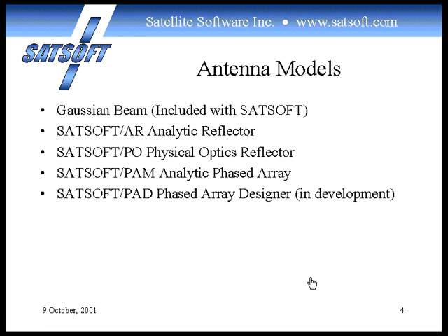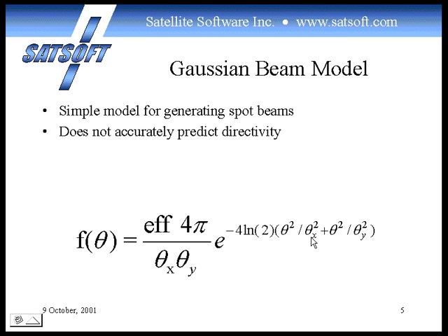The Gaussian beam model is included with SATSOFT. All of the rest of the models are optional. There's two reflector models, a simplified analytic model and a high-fidelity physical optics reflector model. There's an analytic phased array model, and there's also a more fully featured phased array program, which is still in development.